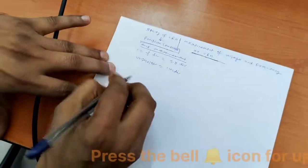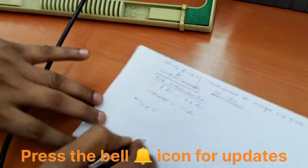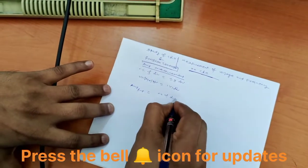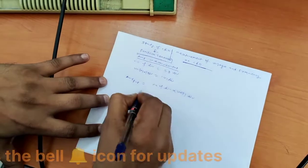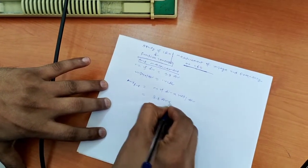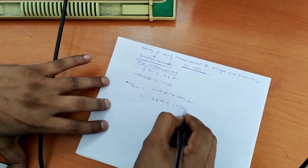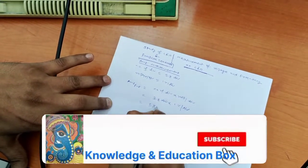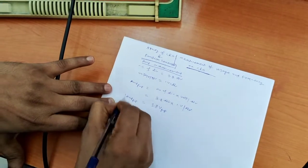Now we have to multiply both of these. The amplitude peak to peak will be given by the product of these two: number of divisions multiplied by voltage per division. The number of divisions was 3.8, so 3.8 divisions multiplied by 1 volt per division. The division is in the denominator, so the unit will cancel out, and you will be getting 3.8 volt. And this is peak to peak amplitude.